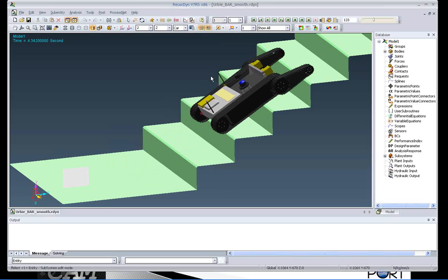But then as you build the first prototype, you want to check loads being generated from the prototype compared to the loads from the simulation, and make sure that those loads are matching. An important aspect is that there's a cost to measuring loads experimentally, and as I mentioned earlier, some loads are not readily measured experimentally.